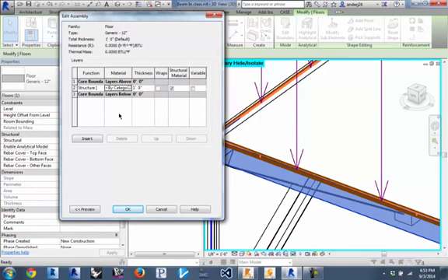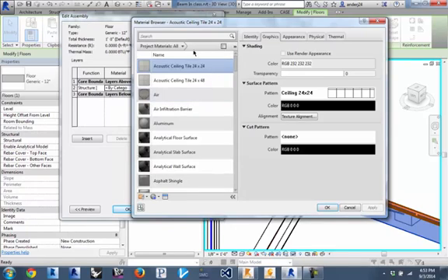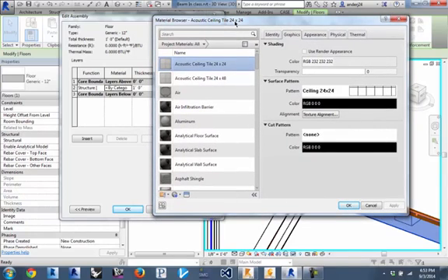So you could do an analysis of a generic floor assembly, and then say this is a generic 12, and then apply a material to it. Say this is all lightweight concrete, and then you do generic 12 with regular weight concrete. Those are going to have two different parts, but you can do it as a generic sort of chunk. So you might not necessarily need to go down to a real finite level. So that's another way where you could do sort of iterative design based on that, and see how that affects the member sizing in Robot. Does that make sense to everyone?